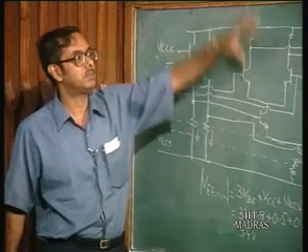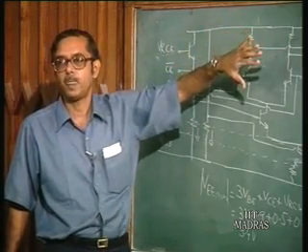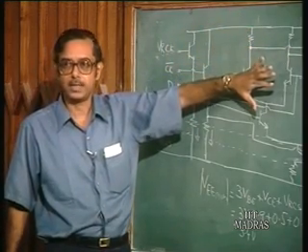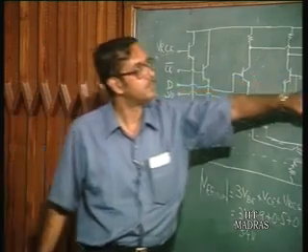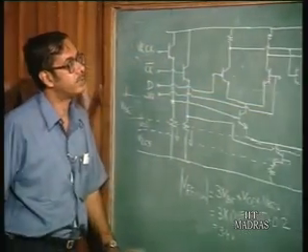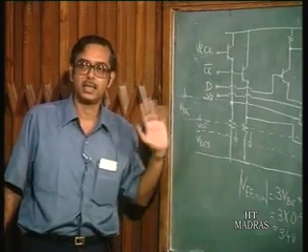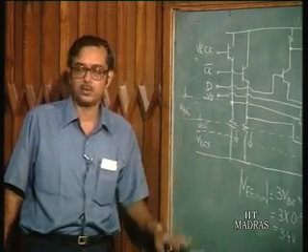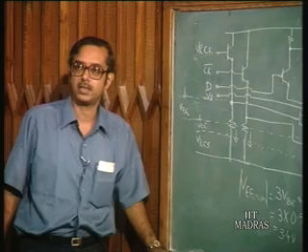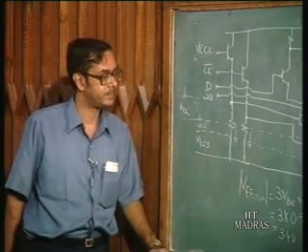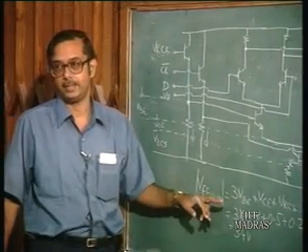The VR also has been shifted up by VBE. Okay, so there is no problem. As such, of course, you may have to be careful about the fan out, as we had discussed in the first class, but there is always a trade off. Okay, so here we are looking at low power dissipation. Okay, so what happens to VEE min?